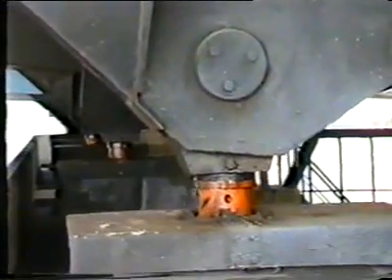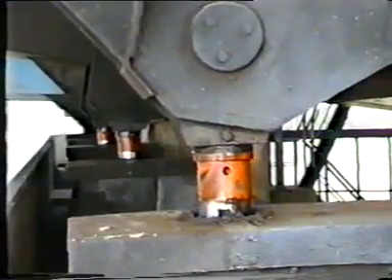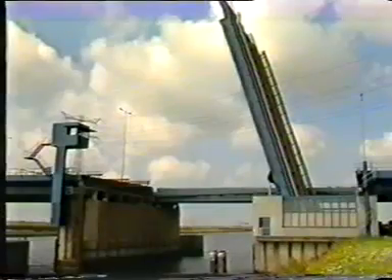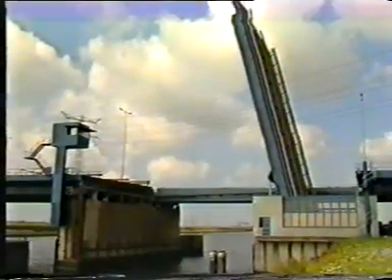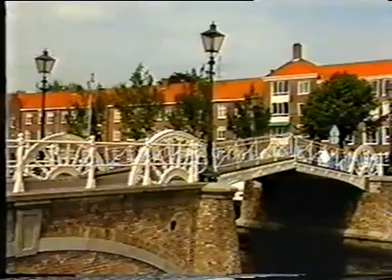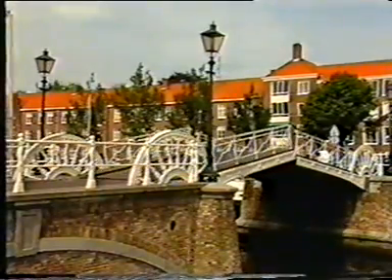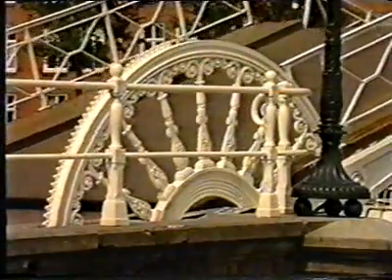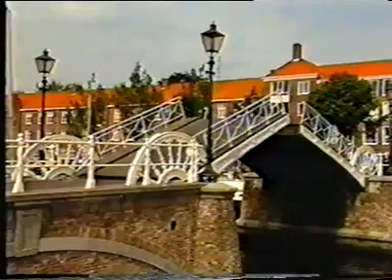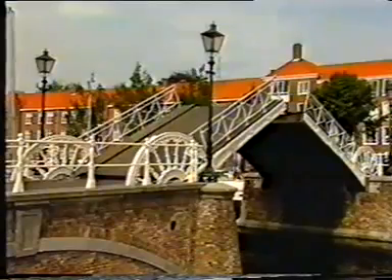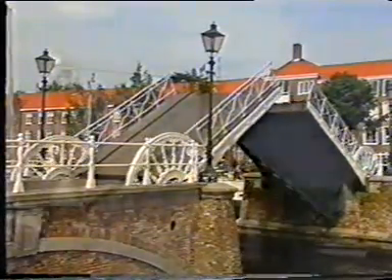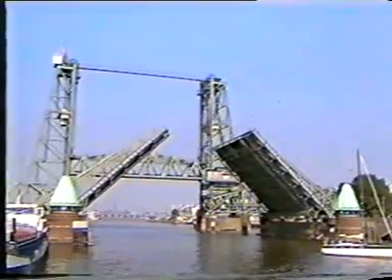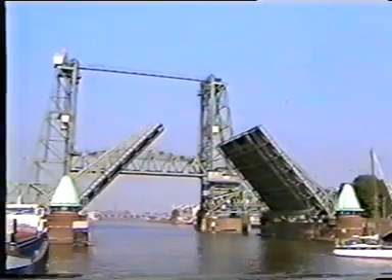The next step in the development is a direct operation of a bridge by means of a hydraulic system. Single-leaf bascule bridges are possible as well as double-leaf bridges. In this way, a greater waterway width can be obtained. An unrestricted air draft can be achieved with a bascule bridge. In a lift bridge, a greater waterway width is possible, but the air draft is limited.